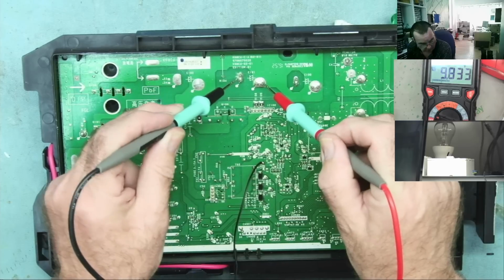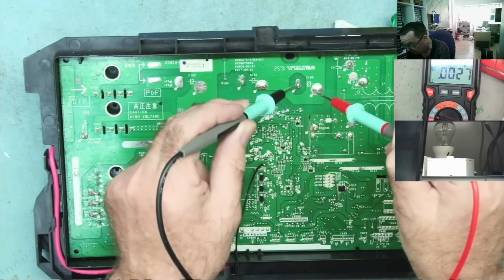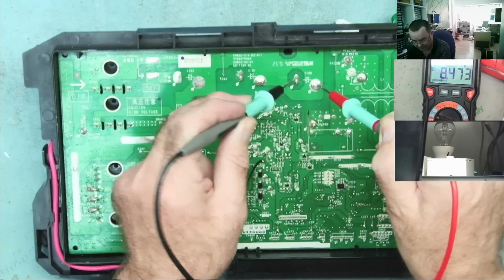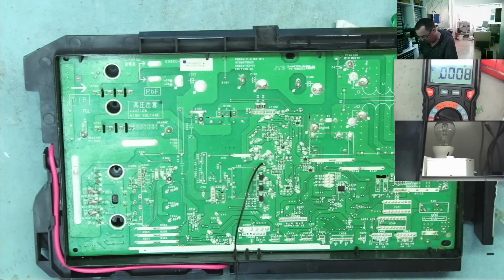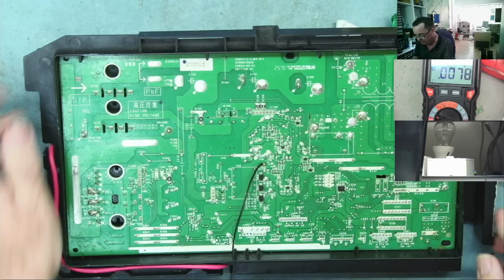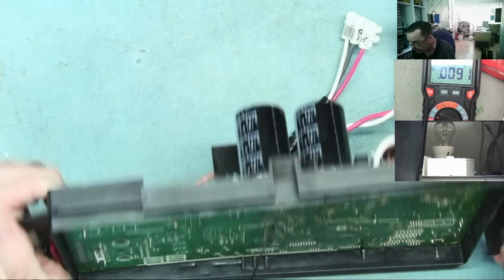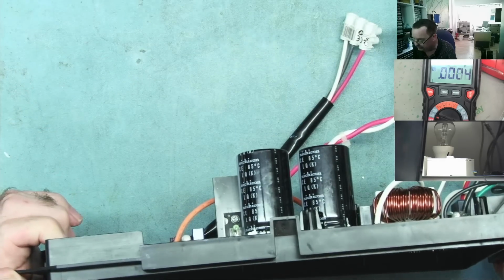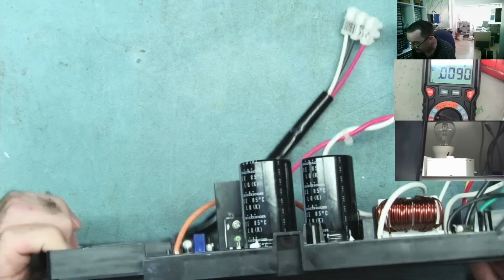Nothing. Oh, 9 volts. So this powered up, in actual fact. We can say that. There's some voltage in there, so there's not a short. It obviously drew some current. Those are very large capacitors. Could just be the charging current, especially because remember everything's going through that 30 something ohm resistor.